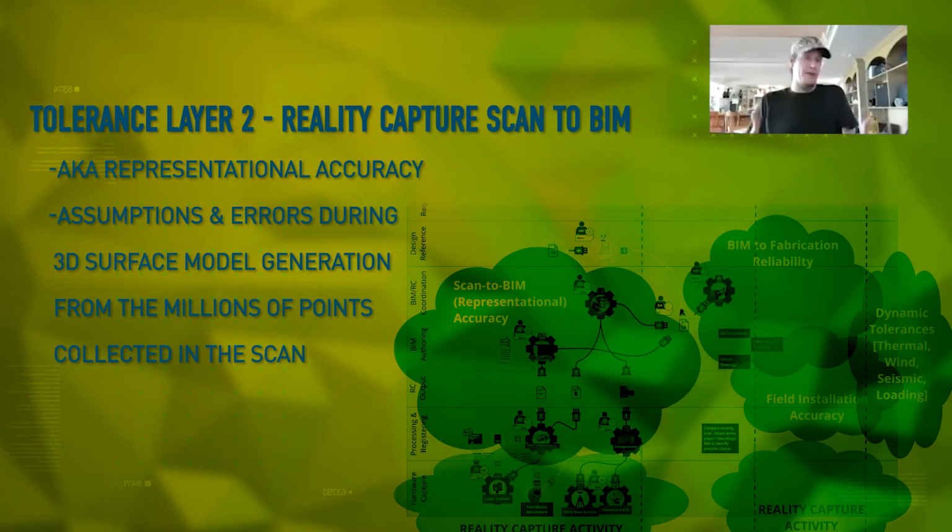And so this is where survey control is really important, because with scanners, if you think about the spacing between scan stations, that spacing is equivalent to the length of your individual measurements, from a tolerance or error standpoint. So if you're spacing every 20 to 30 meters or every 20 to 30 feet, that's that many measurements.